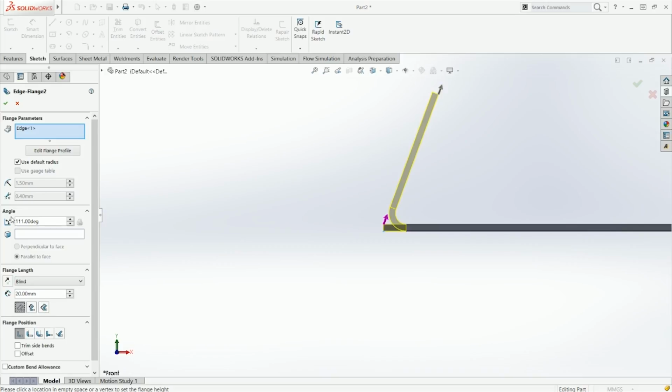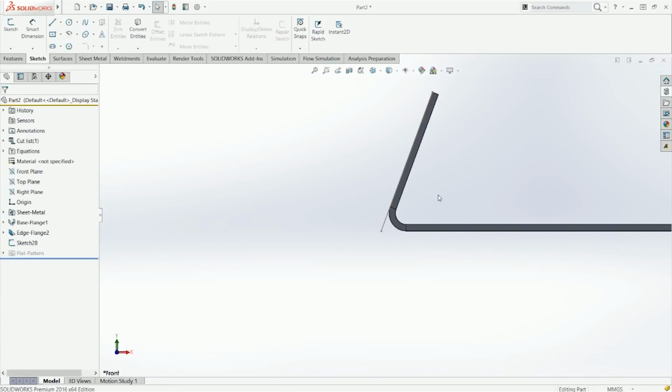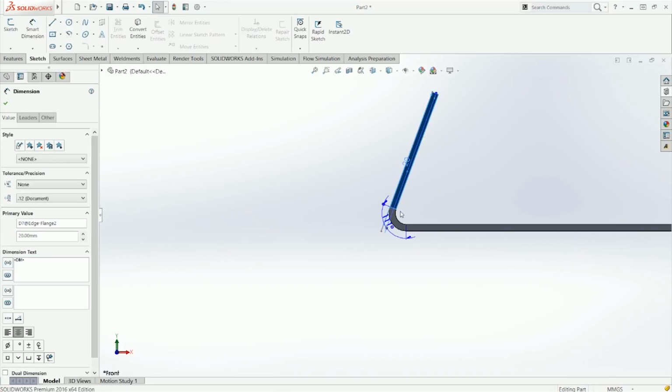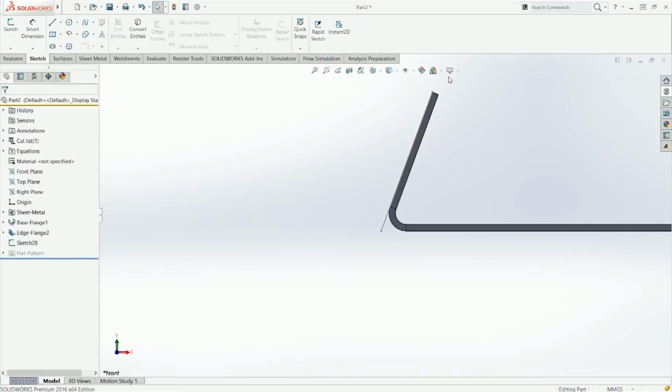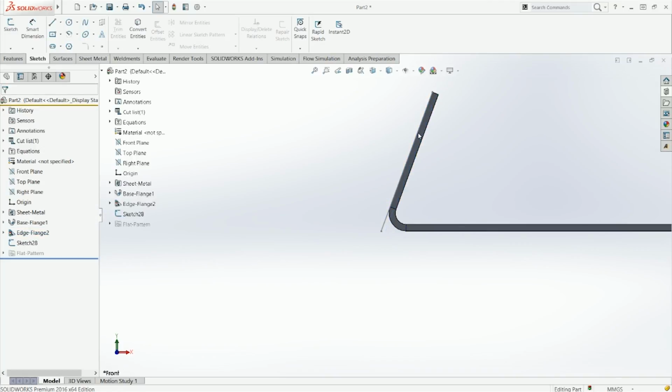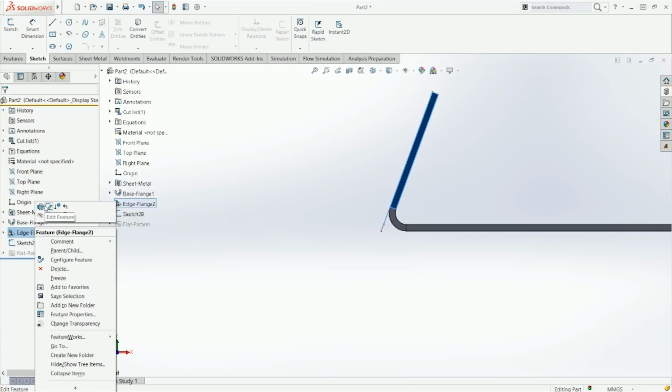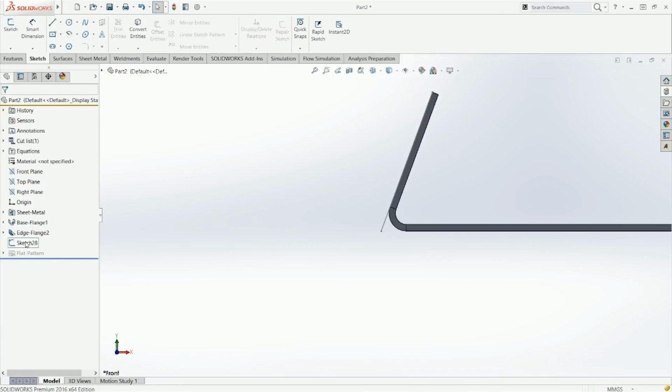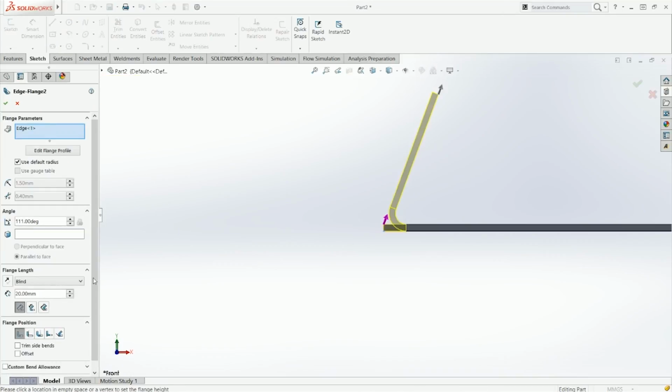And even if you don't, you have to be careful about how you define your parts completely, because if you want to edit this and you were meant to have the dimension from this edge to that edge instead of from the outer auxiliary line, you will probably measure in your assembly fit 20, but once you define this as 20, you'll see that they will not meet, and that's just because of the way that you've defined your parts. So that's something you have to take into account.